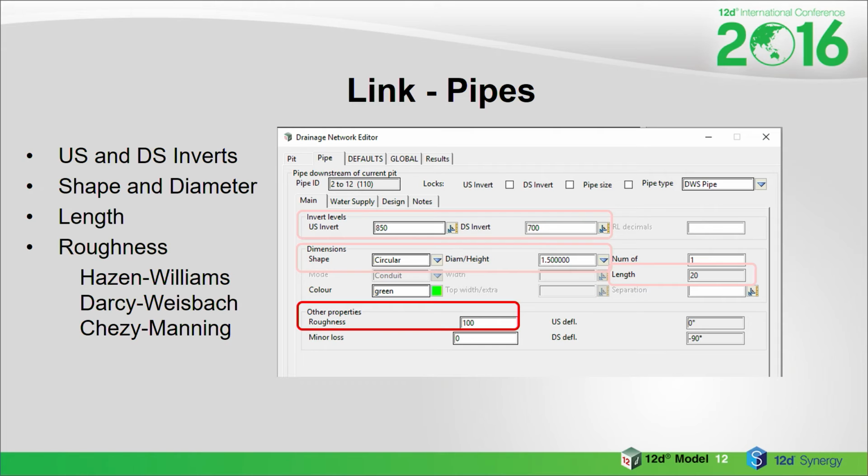It's probably the main difficulty with Darcy-Weisbach that there's not a lot of information on the exponent you use for the coefficient, or the epsilon that you use in the coefficient. But I guess you could always use 0.7. So Chezy-Manning is probably most common for open channel flow, but yeah, if that's your favourite, you can use it. Okay. The other information we associate with a link is a minor loss, so that might be for a reducer or a bend or a meter or some component in your network that will affect flow in some way.